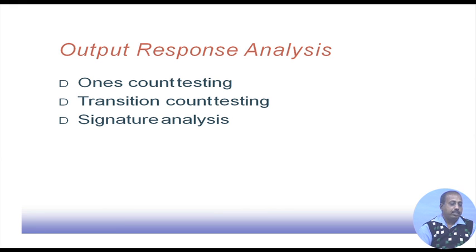Next, after the pattern generator, the next important module in BIST testing is the response analyzer. What is happening is that from the circuit, on the application of every pattern generated by the pattern generator, some response is generated. Now, we cannot store all those responses in the circuit itself, because the pattern generator was running in an autonomous mode. It was generating the patterns, they were getting applied to the circuit, but the responses cannot be stored in the circuit, because that will be huge, for the sake of comparison.